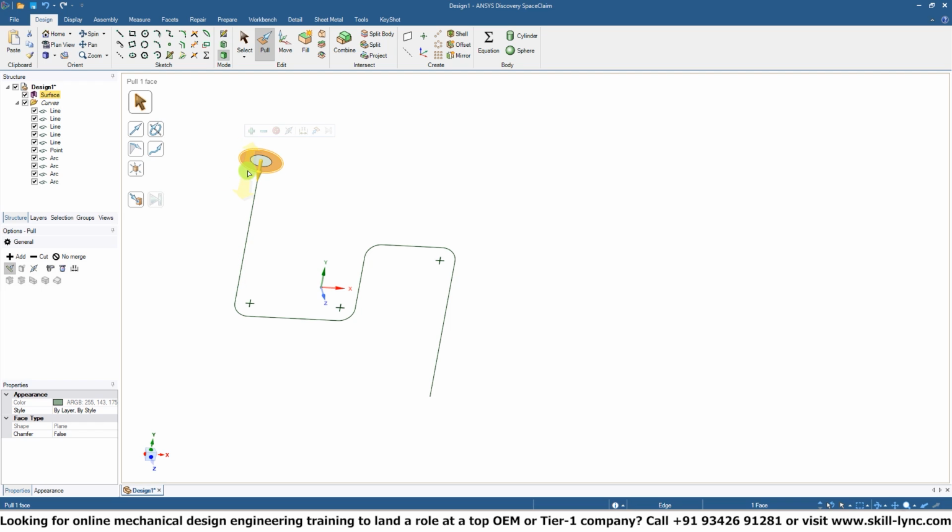We select the outer diameter of this pipe. Now we can select the sweep path. So just select holding Control or Shift and select all the areas or sections of the sweep profile that we'd like to define. We can put up to, if you wish, up to this point, or sometimes if that doesn't work, you can simply just extrude it. You would simply extrude it, but we encountered a common problem over here.